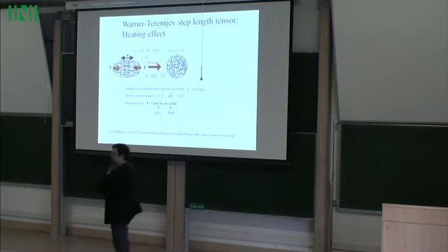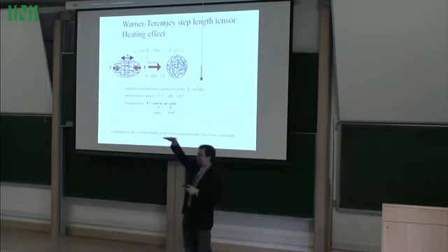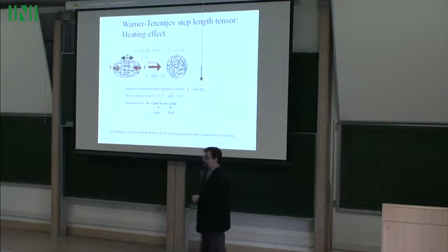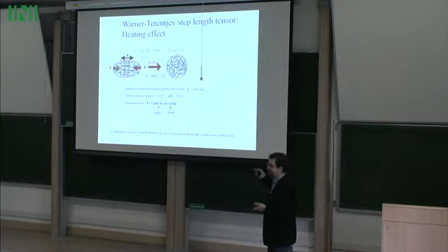For example, if we do the same experiment but polymerize at high temperature, 100 degrees, then at high temperature the film will be flat, and then you would cool it down, it will develop a profile, and that profile will be exactly opposite to what I showed for heating, just because whatever was contraction now would become expansion in the same direction. So yeah, we did some of those, but the problem is that at high temperature doing chemical reactions is kind of tricky, so this is why we start at room temperature.